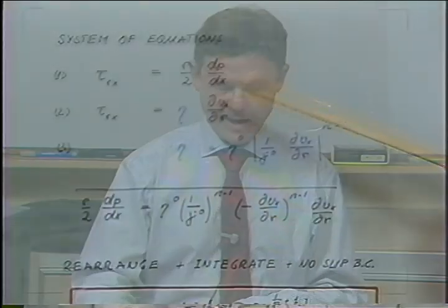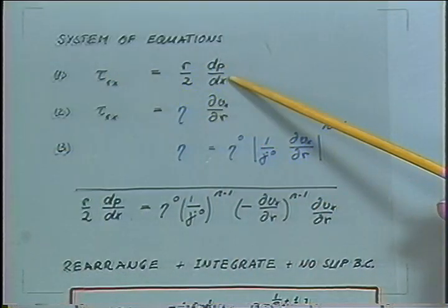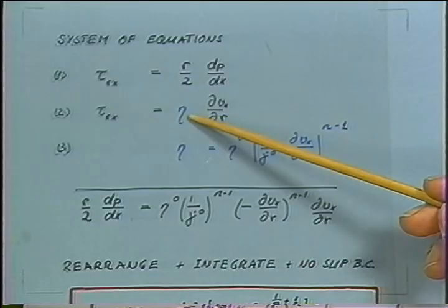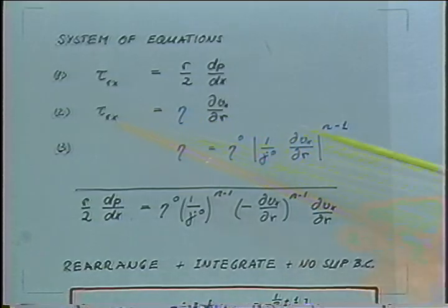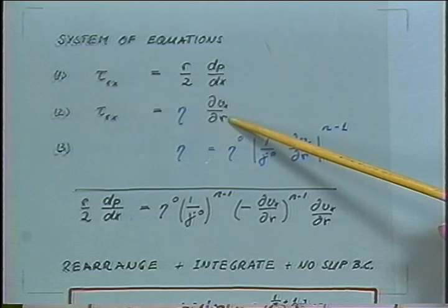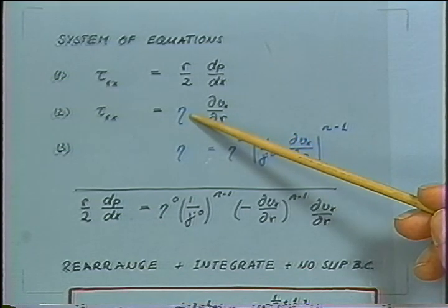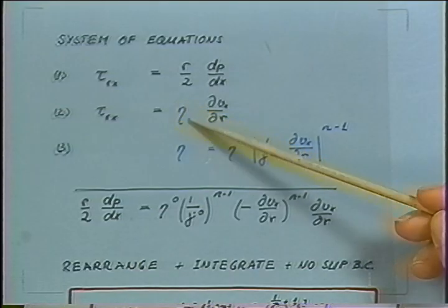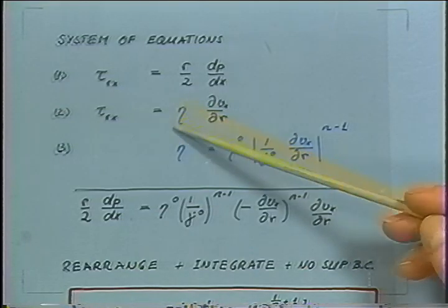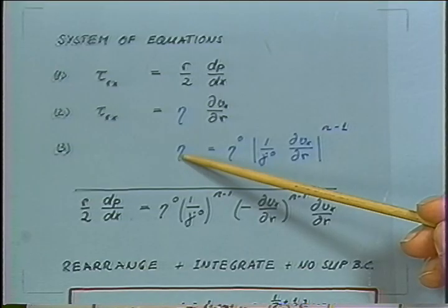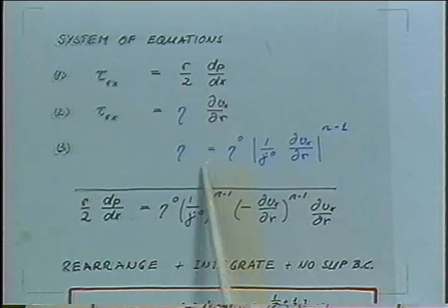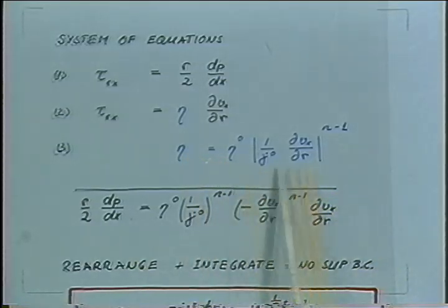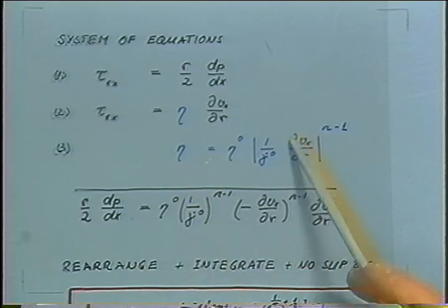And we can combine now this equation for the shear stress, which we just calculated, with the material function, where we would say the shear stress is given by the local shear rate multiplied with the local viscosity. And the viscosity locally depends on the shear rate. In this case, the shear rate is not constant. We have to introduce now the function for the viscosity, which captures the shear thinning phenomenon, the shear rate dependence. And I did this by just describing it with a power law. Yeah, the viscosity is given by a power law.